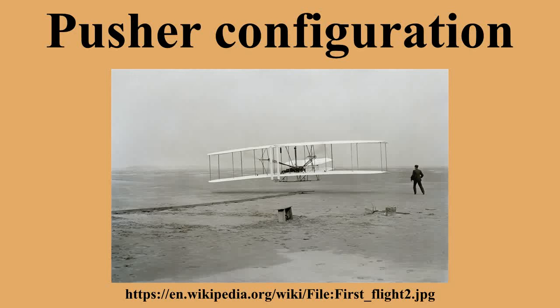Engine and safety. Engine location in the pusher configuration might endanger the aircraft's occupants in a crash landing in which engine momentum projects through the cabin. For example, with the engine placed directly behind the cabin during a nose-on impact, the engine momentum may carry the engine through the firewall and cabin, and might injure some cabin occupant.